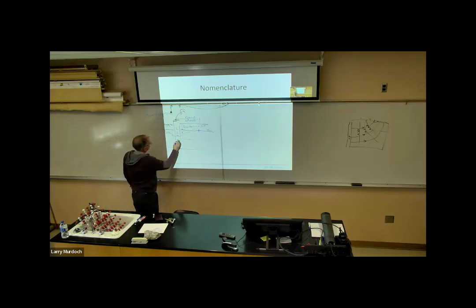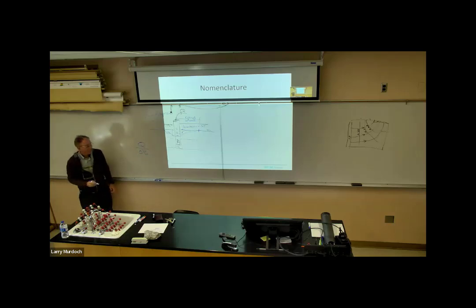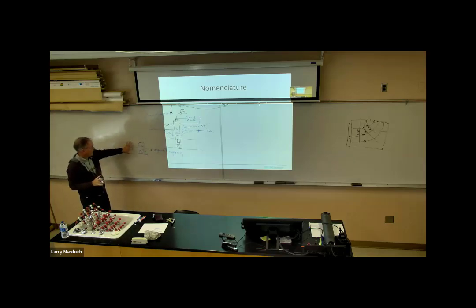Okay, so we're pumping water out at this rate, and that pumping action causes drawdown in the well. The ratio of the flow rate coming out of the well to the drawdown in the well, that's the specific capacity. If we pump the well long enough and it goes to steady state, that means that the drawdown isn't changing anymore.